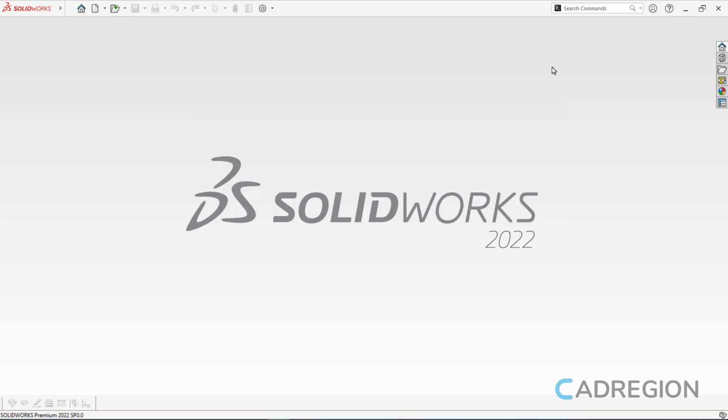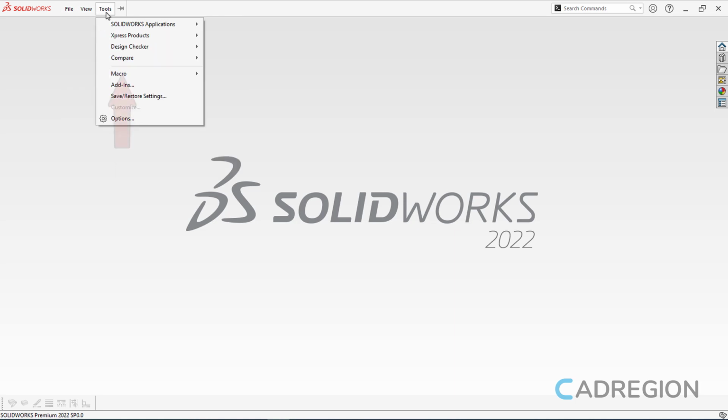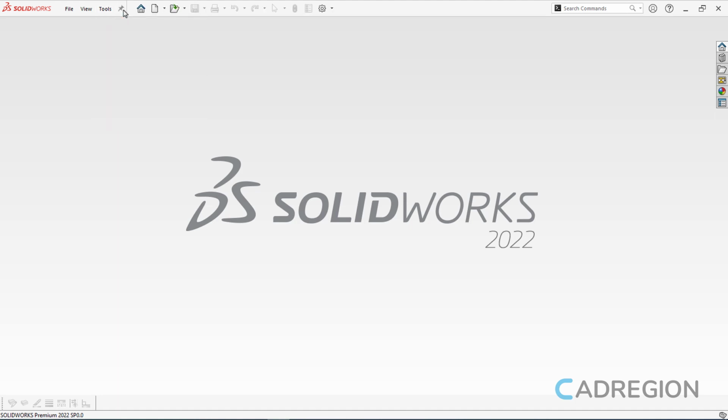If I hover the cursor over the Solidworks icon on the top left of the window, the menu of the application appears. If you want to pin the menu bar, then all you have to do is to click on the pin icon on the right. On the right of the menu, the Quick Access toolbar appears. In the Quick Access toolbar, you can find useful tools like the New icon, the Open icon, the Save icon, the Print icon, the Undo icon, the Redo icon, the Select icon, as well as the Rebuild icon, the File Properties icon, and the Options icon.